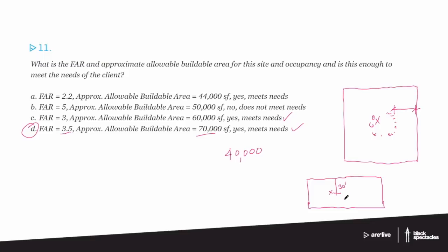I think it's 10 meters, which is about 30 feet, but it might be a different number. That came about because people wanted operable windows and wanted to be near sunlight. So a shallow footprint means everybody is near a window. You can't be somewhere in the plan and not be reasonably close to one.